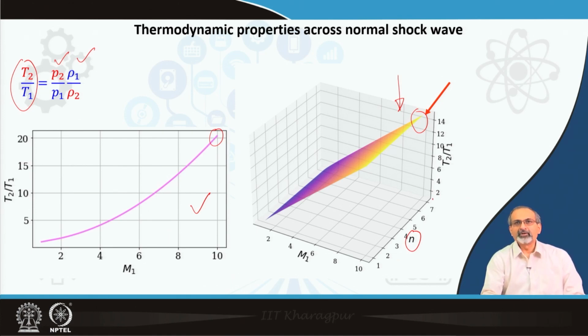Not that we will be able to discuss these aspects in much detail before we undergo more detailing on the thermodynamics aspects from a statistical or microscopic point of view, but still one comment may be made: as we approach higher Mach numbers and more energy modes get excited, the energy content of the gas will essentially get distributed over different energy modes, and the temperature that we see over here is essentially reflecting the energy content that we have in the translational mode.